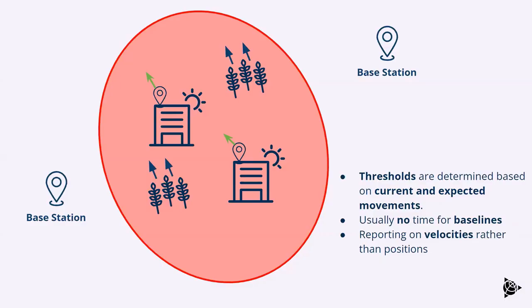And then we also want to understand when things are accelerating and have an understanding of how it changes. The biggest difference here is that this is a reactive setup. And so it's not always possible to determine your baselines and thresholds ahead of time. So what you want to do is set up and measure for a little while and understand how things behave as they do normally. And then you're going to be reporting on things like velocities instead of just raw displacements or coordinates, because you expect things to be moving in that dynamic environment.